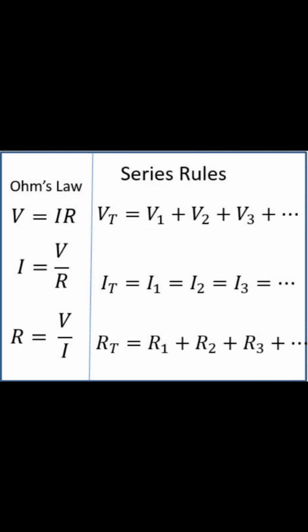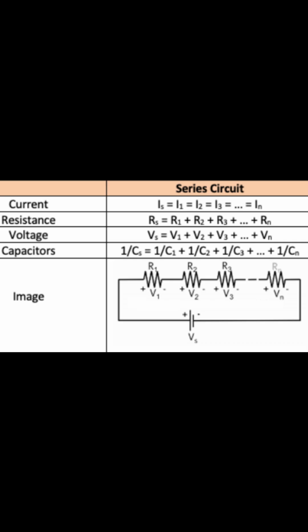8.1 Reducing a complex circuit. When solving a series parallel circuit, often called a combination circuit, you will use all of the formulas and techniques that you learned in Chapter 6 and 7. When one branch of a parallel circuit has resistors in series, you will use the series circuit formulas to turn those resistors into one equivalent resistor.